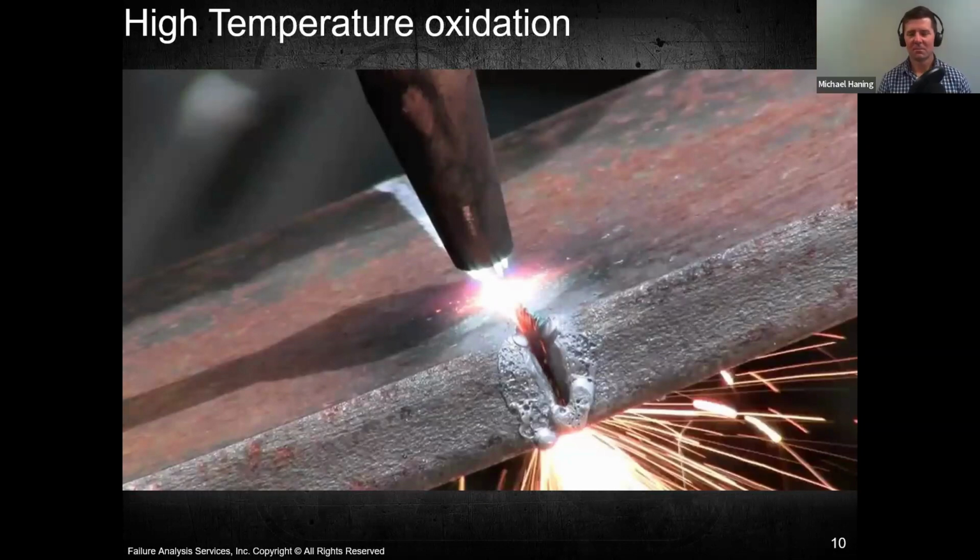So if we hold it there and we let the molecules, the atoms in the surface of that metal, get a little excited because of the high temperature, they start to oxidize. And as they start to oxidize, we're introducing oxygen molecules into that area. Then we can flood it with a lot of oxygen when we hit the oxidizer bar, and it cuts the steel away, right? So if we were to just hold that without hitting the oxidizer bar, it's going to do considerable damage to that surface just because of oxidation and the heat applied to the surface, right? So we see this potentially on different parts in engines.